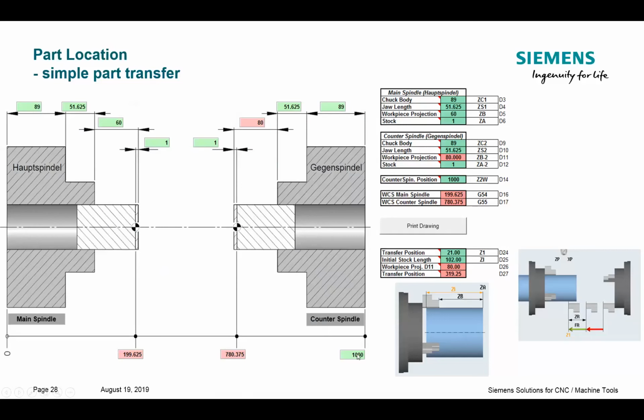A lot of times we refer to this as the park location. This is where I'm going to send my sub spindle to stop and hold while I machine any of the operations in that secondary clamping. So when I jump around, come back to it, and start machining the back op, I'm going to want to send the spindle to a known position.